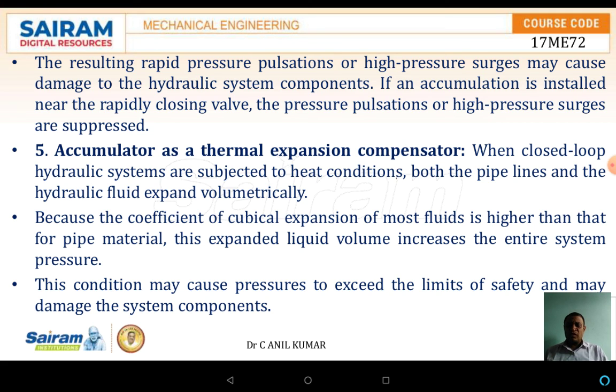The liquid volume increase raises the entire system pressure. This condition may cause the pressure to exceed the safety limit and may damage the system components. For that reason, accumulators are used as thermal expansion compensators.